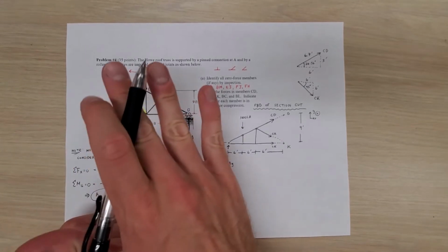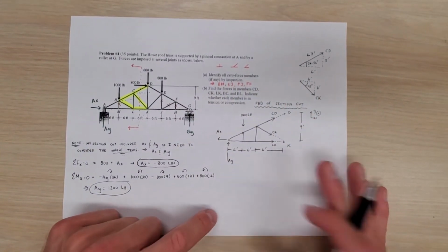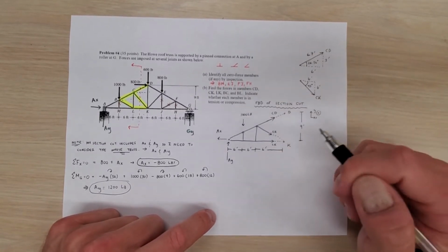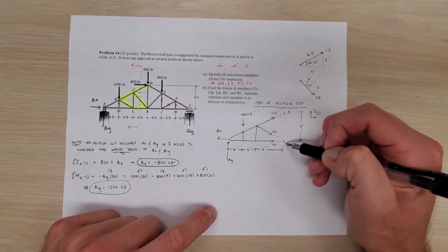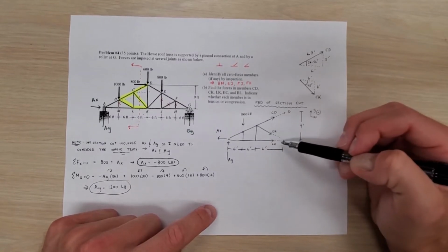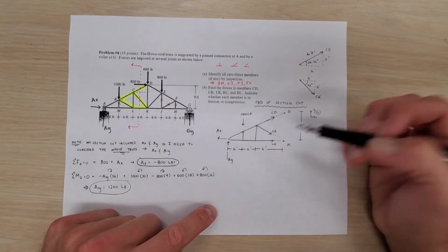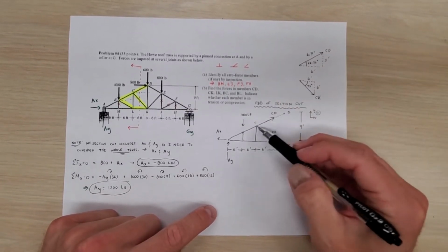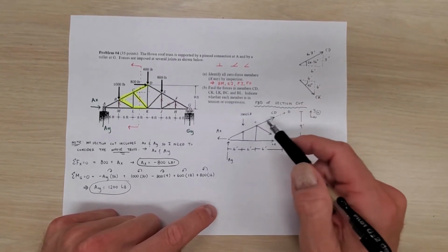So anyway, after we've done the zero force member stuff, we'll come back down here to our free body diagram, and see that we need to solve for CD, CK, and LK. Now, the best thing to do in a method of sections cut is to either take the moments about point K or about point C. The reason being that if we take the moments about point K, LK and CK both pass through that point, so they won't matter. If we take the moments about point C here, then CD and CK both pass through that point, so they won't have a moment through that point either.